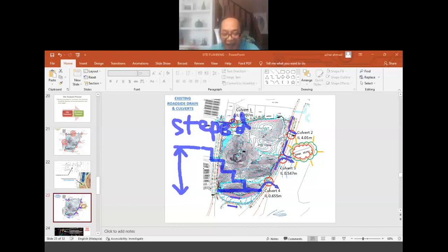Okay, we can use that as a solution, but again, it may be up to a certain limit, maybe around 1.5 to about 2 meters. Okay, 1.5 to 2 meters difference. More than that, it might not be practical. It can be proposed, but I'm not too sure on the practicality side of the discharge of the drain. So try not to have too big a difference.